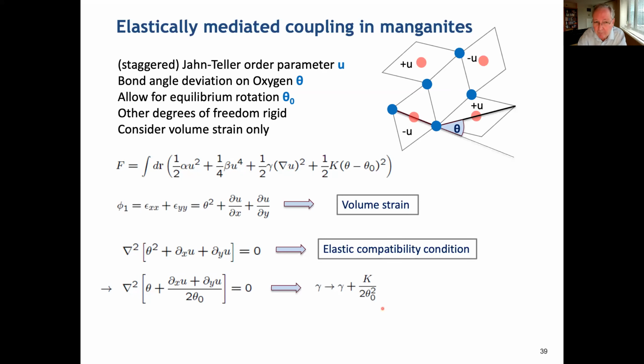And in this very simple model, you see that the system becomes infinitely stiff as theta 0 goes to 0. And so that's the physics that I was trying to describe before, that as you remove the ability of spatial fluctuations to be screened by rotations, then you get this stiffness. And by the way, this is just like the stiffness of an Euler strut. If you take an old-fashioned meter rule and push on it from the end, it's very stiff until it bends, and then it becomes softer.